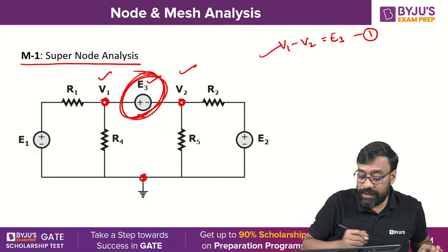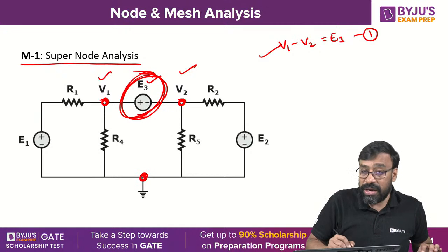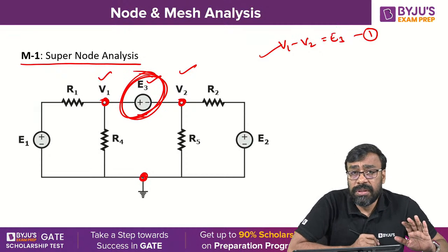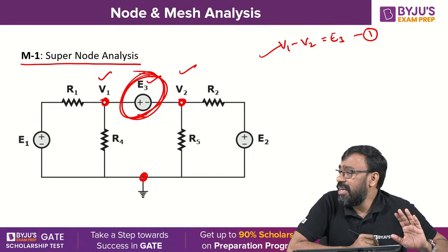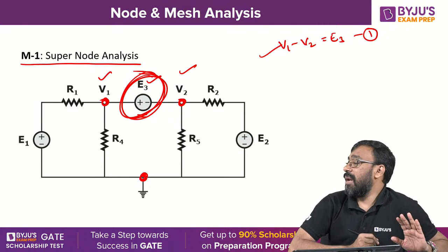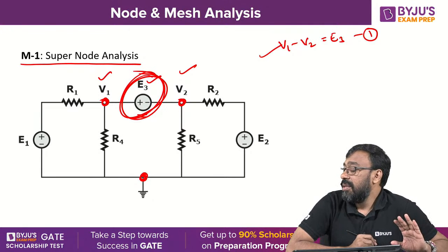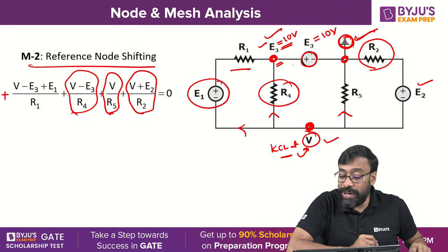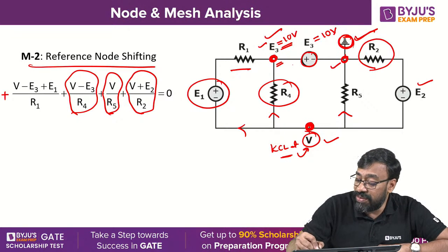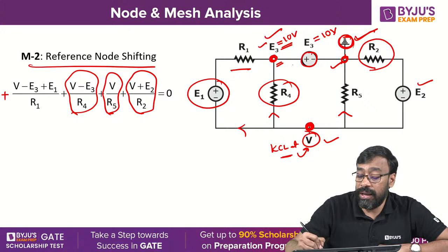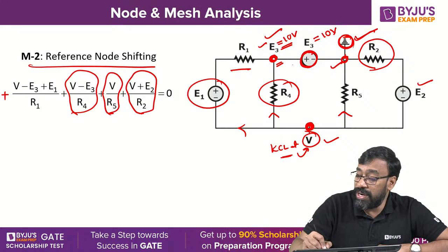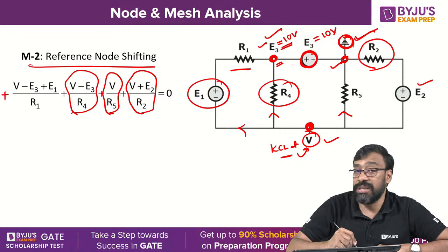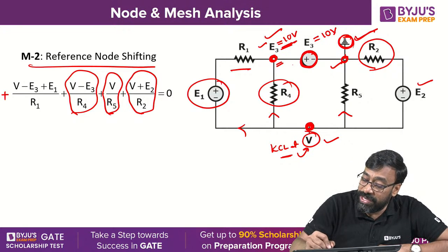You understand? Okay. Three nodes are there. Always three nodes are there. Three nodes, two equations, generally that is what the n minus 1 formula says, yes, that is true, but that condition fails, Ravi Shankar. I have proven that if I select this one as a reference node, because it is an ideal voltage source which doesn't have any series resistor, you know this voltage.